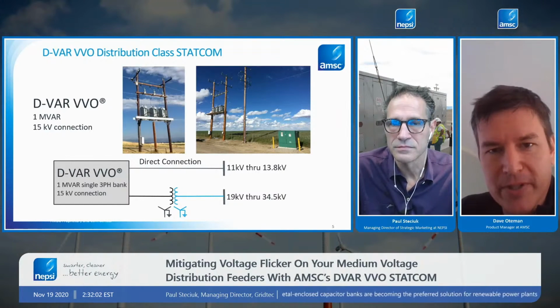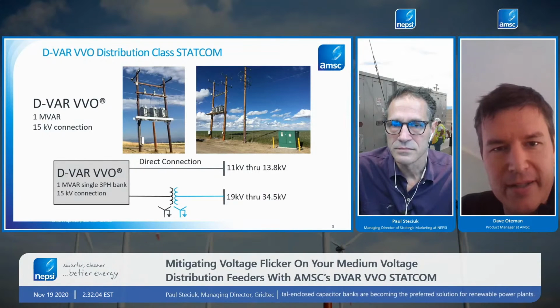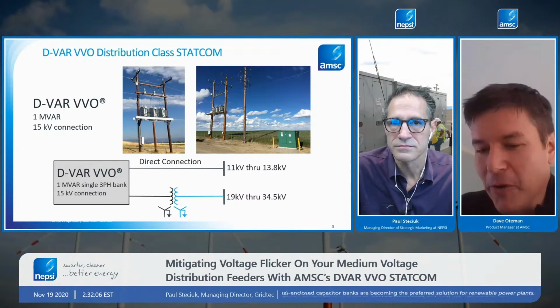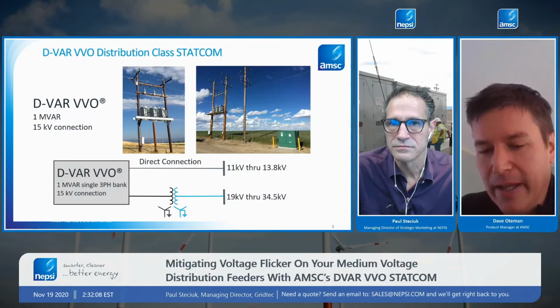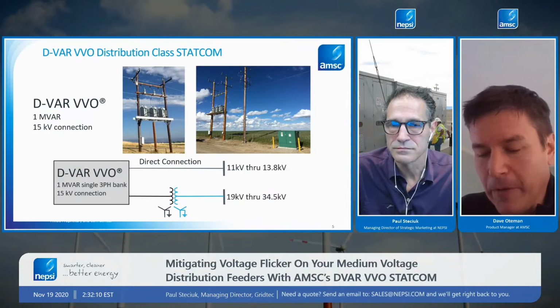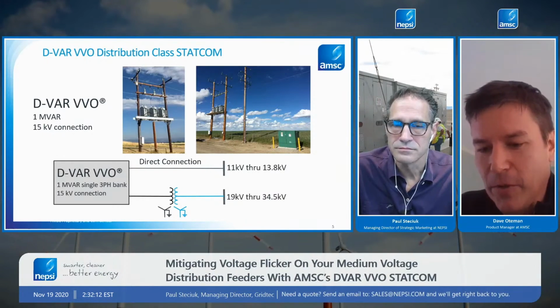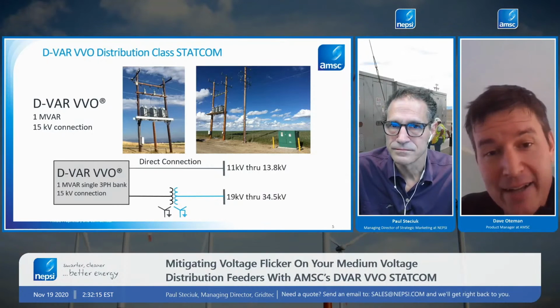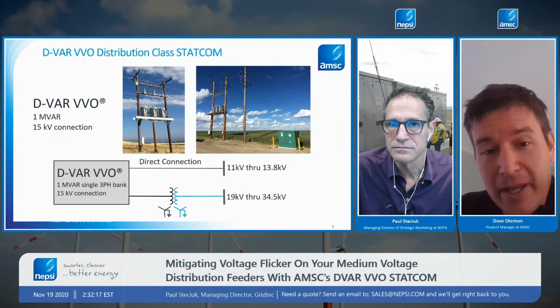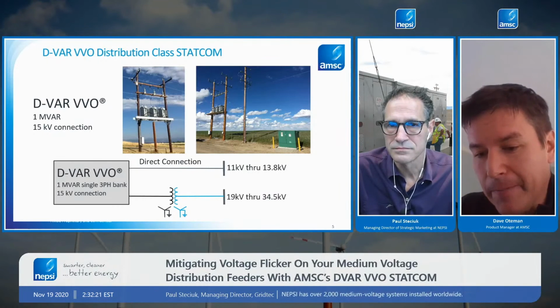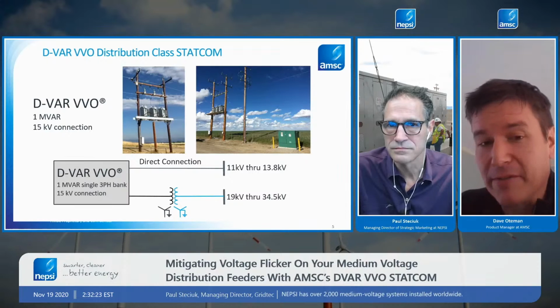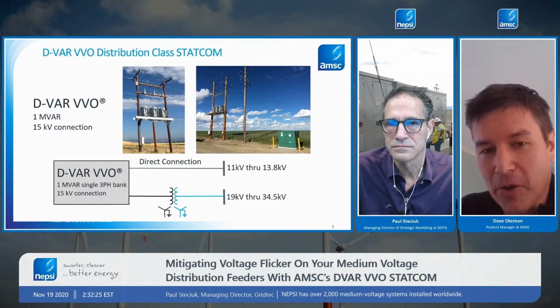So in the distribution system, it is common that there'll be different amplitudes on different phases, and then it's a simple configuration at commissioning to tell the STATCOM to independently control each phase versus a positive sequence control mode. So there are two control modes possible: positive sequence and then independent phase.